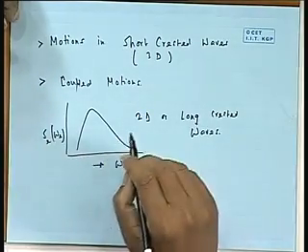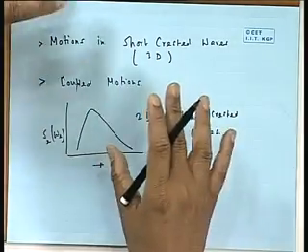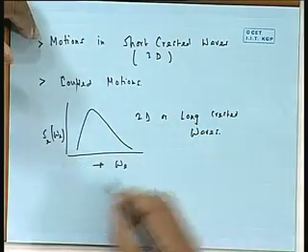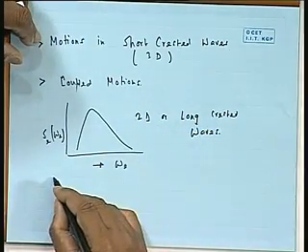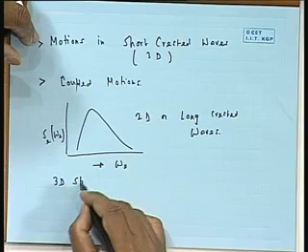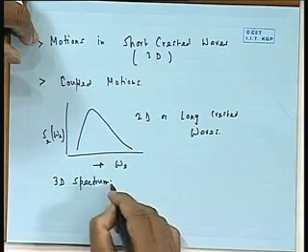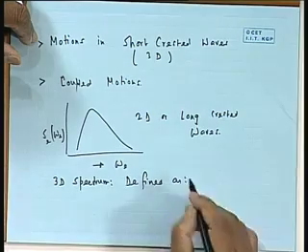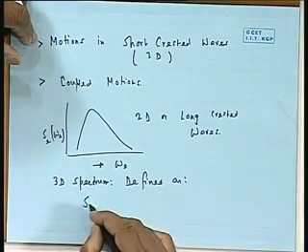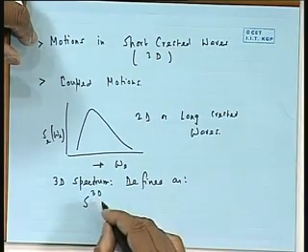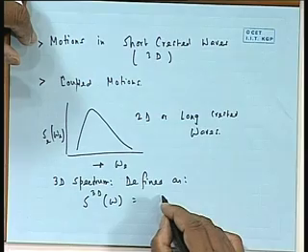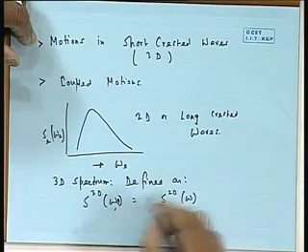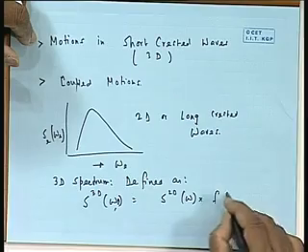a spreading function and taking also the fact that waves come from all directions. Basically we have defined that 3D spectrum S 3D omega is equal to S 2D omega, well there is a theta here, multiplied by F theta.